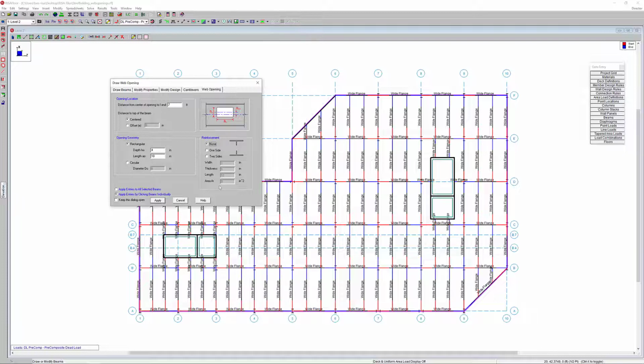Next, we want to go ahead and define reinforcement. So we can either choose to not reinforce the opening at all, choose to add reinforcement to one side of the opening or to both sides of the opening. And you can see here when we choose reinforcement on either one or two sides, we can choose the width of that reinforcement. So in this particular case, I'm going to choose one side. And let's go ahead and define a width of 1/2 inch. Our thickness of plate in this case will be 1/4 inch. And then let's set our length of 16 inches.